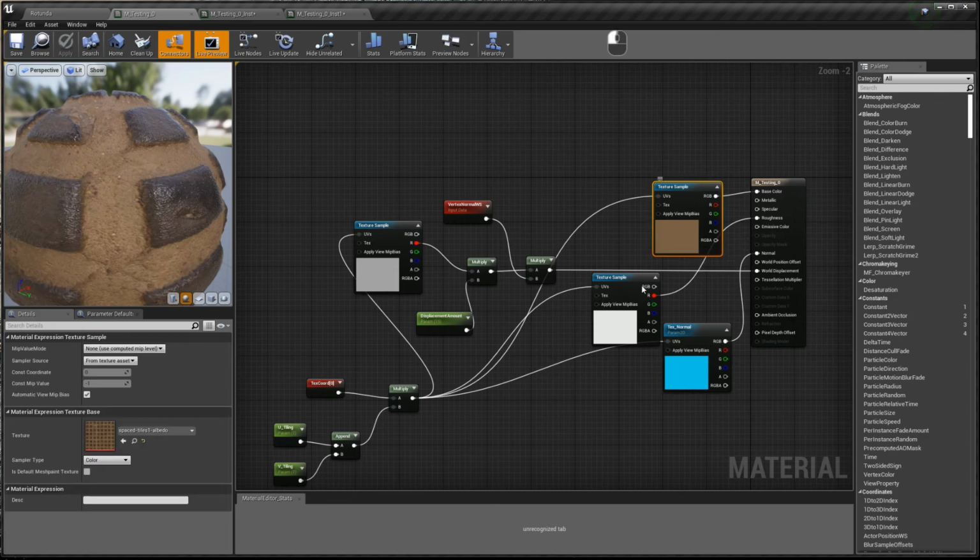You can override these other texture samples as new parameters. You might want to add some extra ones, for example the metallic channel, which was not needed for this material. I will be taking a close look at the plausibility of the materials that you create. For non-metals, you have a lot more free range when selecting the base color, but when it comes to metals, I will be expecting some very specific values here. Note that there might be textures that have those specific values in them.